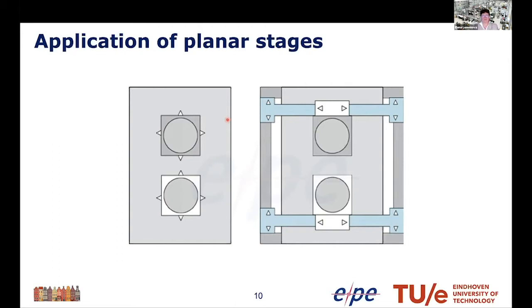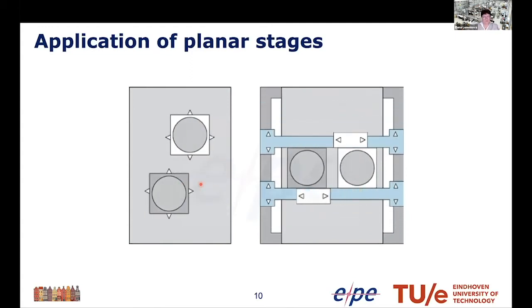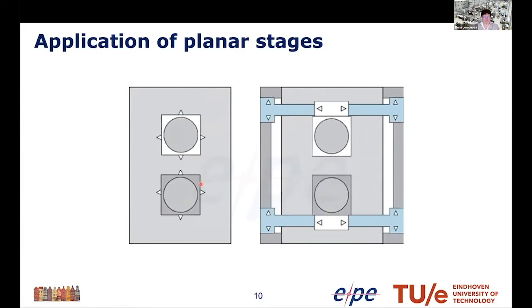It is subject to many additional parasitic phenomena like backlash or friction, and to eliminate that, we use the concept of planar motors, especially without cables, which means we have to eliminate cables for the delivery of power and the delivery of cooling to the actuators. We are thinking about the concept of so-called magnetic levitation above the coils, which will be placed on the stationary platform, and the small platforms with the permanent magnets beneath will be freely levitating on top of the coils.